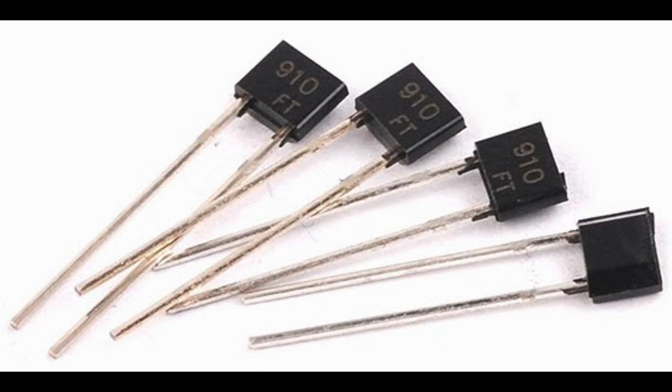6. Voltage to frequency conversion. Some VCFs can convert control voltage to frequency, creating unique and expressive modulation effects. As the control voltage changes, the filter's behavior shifts in response. 7. Applications. Voltage-controlled filters are used in electronic music production and sound synthesis to shape sounds in real time. They can create effects such as filter sweeps, resonant sweeps, and evolving textures. 8. Filter orders. VCFs can be designed as different orders, such as first order, second order, etc., affecting the steepness of the filter's roll-off and the slope of its frequency response.